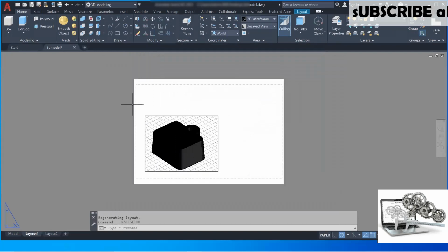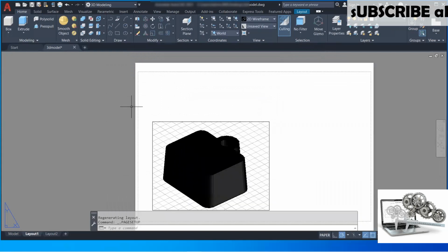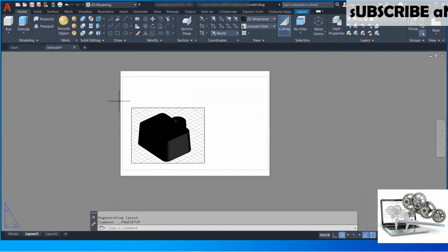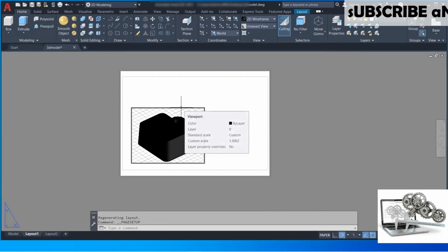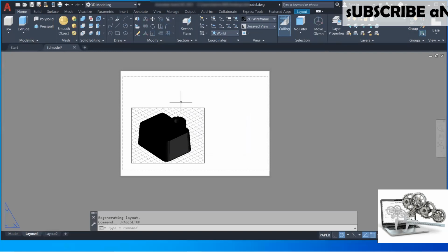Here comes our paper which is set up for plotting. This is a dotted area which is a printable area, and the viewport which we are looking at, that is a single viewport given here, we have to delete that.